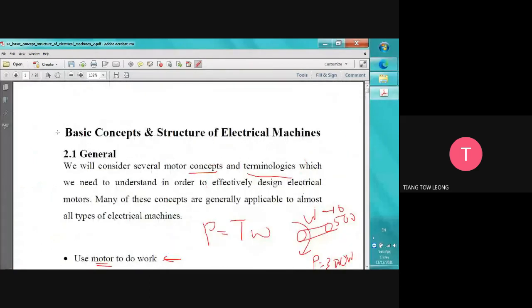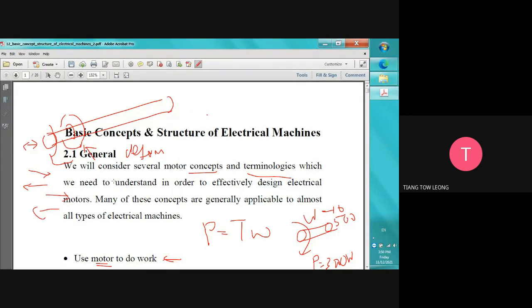For example, this is the shaft. Okay, this is the bearing. If the bearing becomes deformed, becomes like this, if the bearing rusts and deforms, then when this rotates, it will vibrate and move around like this. Sometimes it moves there, sometimes here, sometimes there, sometimes here. Then it becomes eccentric.